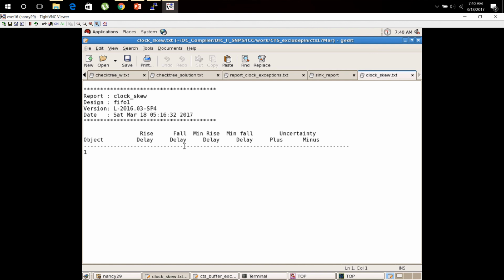For all those fine tuning instructions, we can always man the commands, and we can get to know what different types of fine tuning options we have to perform the skew removal from the design, so that we can continue with the conformal tools for formal verification, and so that our design will be ready to go to the foundry.